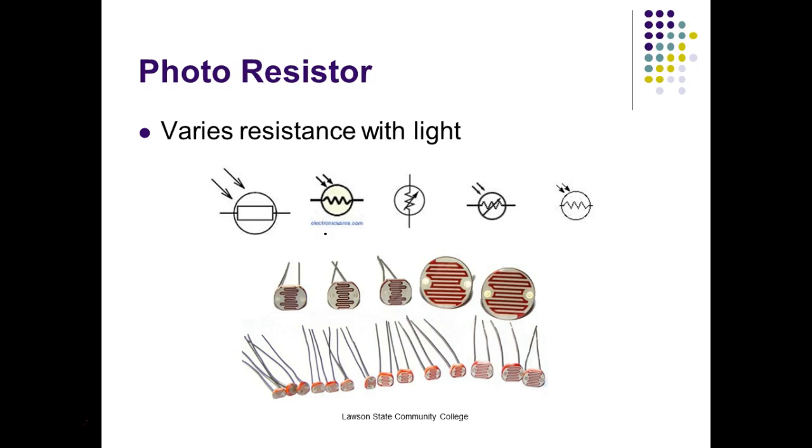It's just like the size of the thermistor. So if we was to look at the data sheet on that thermistor, it would give us the maximum amount of power it could dissipate. If you ever let it try to do work that required more power, then that's going to cause a problem, right? You understand? So this is a semiconductor too. A thermistor is a semiconductor, and this is a semiconductor. But what they're doing is, when the light hits that semiconductor, it changes its resistance.